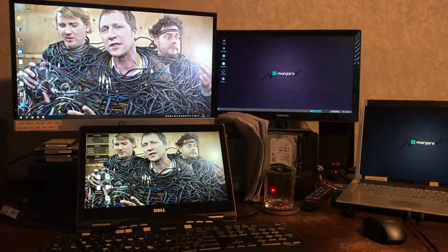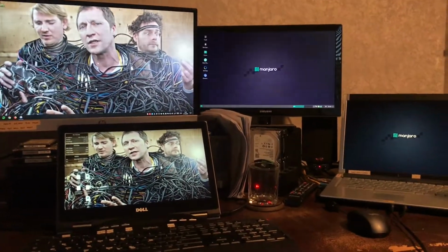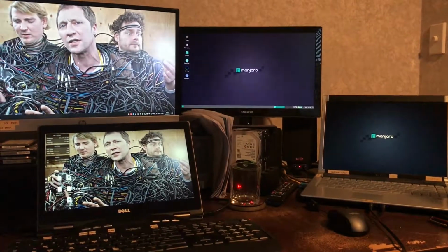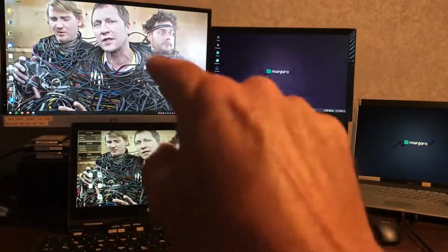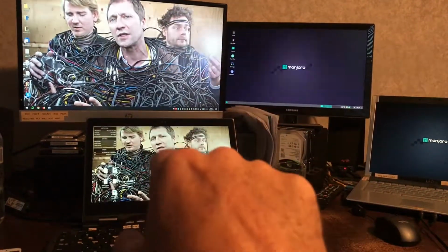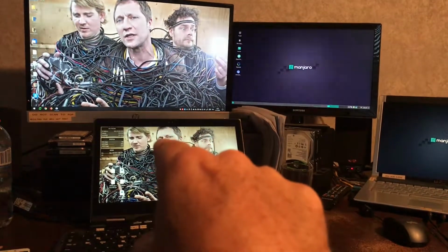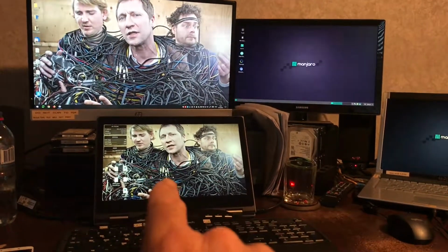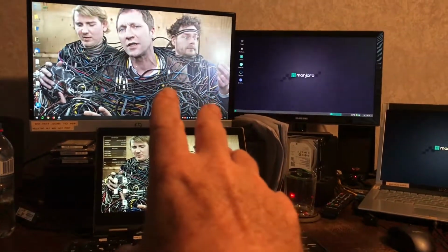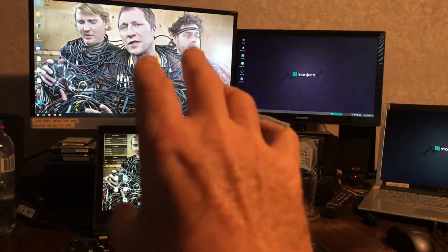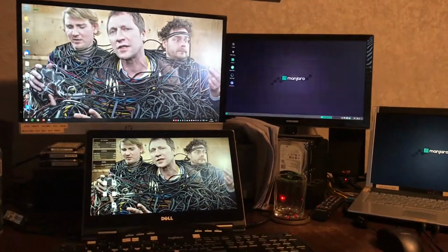Anyway, people will start complaining. You'll know that this latency build-up is occurring when they start saying, mate, you're not getting the last words of your previous over. And then you'll do a test. You'll do that mode switch test, and you'll realise that you hit the mode button, and then there's a 5-second delay. And then you'll hit another mode button or do something else with the radio, and you'll realise that the audio has become delayed by about 5 to 10 or even more seconds.